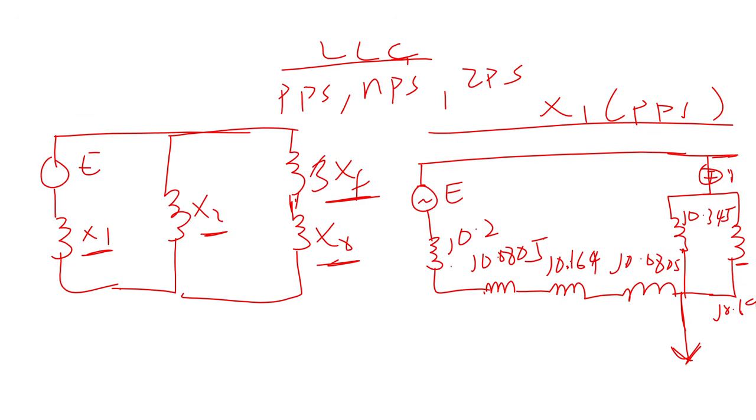And basically, when we are finding X1, X2, X0, it's basically the Thevenin's reactance. So it's assumed the voltages are all shorted. So we can see that the two motors will be in parallel, and then their reactance will be together like that. And then this, and this will be in series. And after that, they will be in parallel with the answer that we got here.